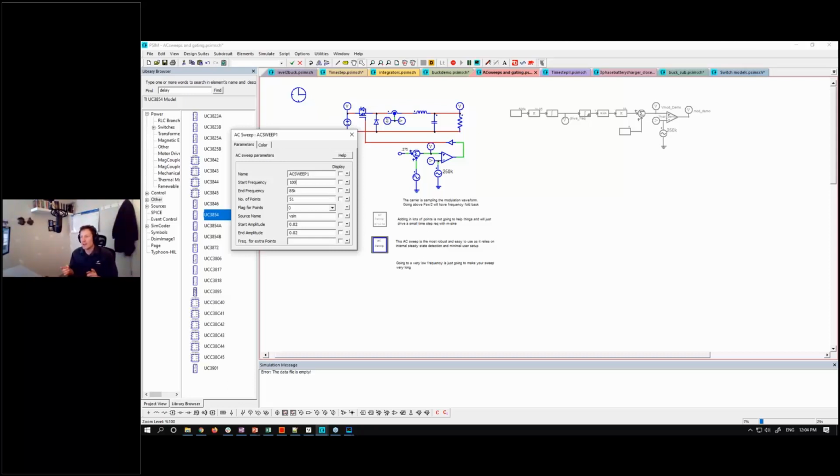you need to recognize how many cycles of the perturbation frequency we need to hit steady state. If it's 10 cycles, at 1 hertz, that's 10 seconds. And if you recall, we were taking 2 or 3 seconds to run 10 milliseconds. So you can extrapolate how long that's going to take if you try and drive really, really low frequencies in there.